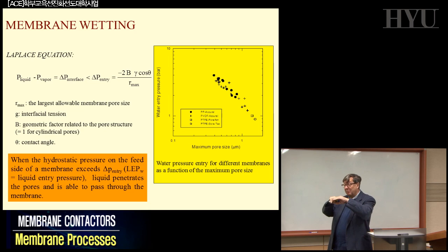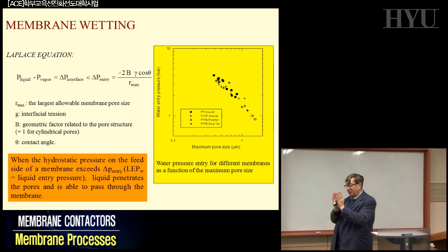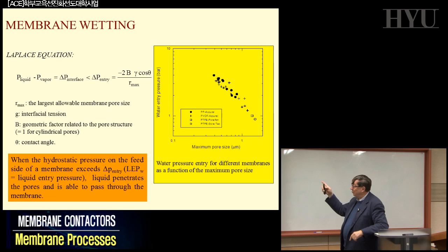However, if the membrane porosity is not very sharp, if you don't have a very narrow pore size distribution, as we expect and as we show ideally in our scheme of the membranes, you can have most of the porosity around 0.2, 0.3, but still a few pores at 3, 4, 5 microns.